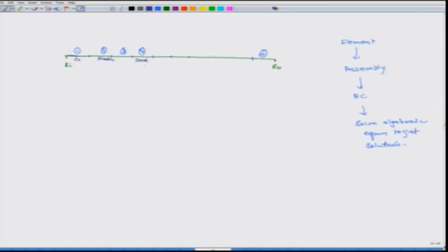But when you have an element level formulation, you can avoid these types of problems. If you have very jumpy material properties, for instance a core of copper, outside you have plastic, then outside you have steel, and so on, what you can do is make the first element or some number of elements such that the boundary of the last element terminates with copper.